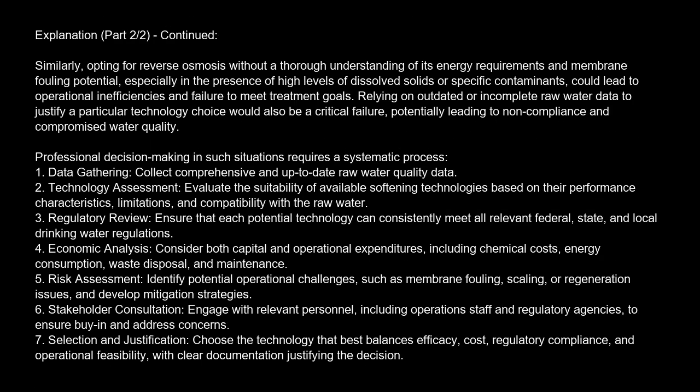Similarly, opting for reverse osmosis without a thorough understanding of its energy requirements and membrane fouling potential, especially in the presence of high levels of dissolved solids or specific contaminants, could lead to operational inefficiencies and failure to meet treatment goals. Relying on outdated or incomplete raw water data to justify a particular technology choice would also be a critical failure, potentially leading to noncompliance and compromised water quality.